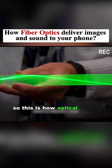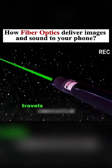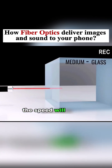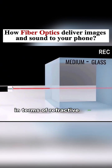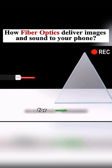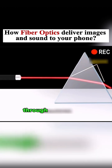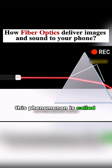So this is how optical fibers work. Elementary school knowledge tells us that light travels about 300,000 kilometers per second in a vacuum. If it passes through a different medium, the speed will change. This change in speed is expressed in terms of refractive index, which also leads to another interesting phenomenon. For example, when light passes through this transparent prism, we can clearly see that the light bends as it passes through the interface instead of staying straight. This phenomenon is called refraction.